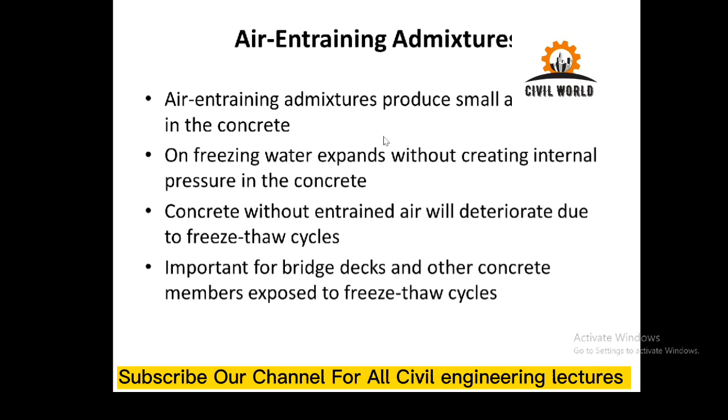concrete. So to avoid this, the air entraining admixture is added while concreting. It produces tiny air bubbles inside the concrete, and when water seeps into the concrete and freezes and exerts pressure, the pressure is diffused into those air bubbles, and thus it doesn't lead to cracking of the concrete.